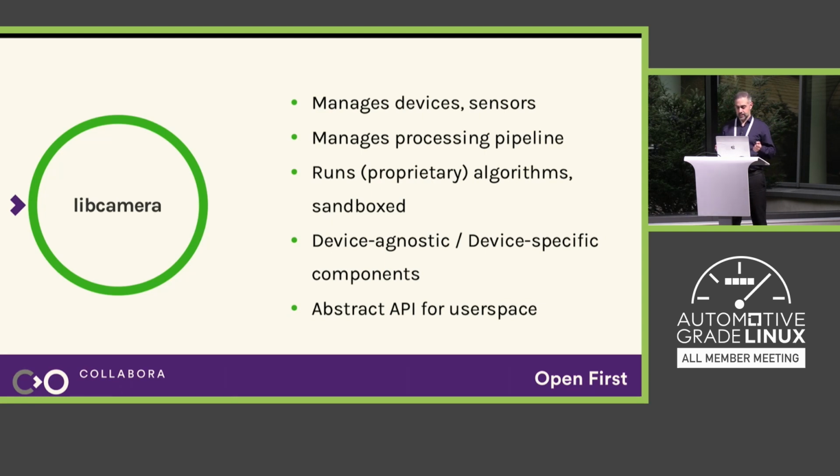So libcamera is a library that provides an API and that is able to manage all of that, all the different sensors, the ISPs, and everything. Because from the Linux kernel, what we get when we enable such a device is lots of different Video for Linux devices, and each of those might be a sensor, might be an ISP.